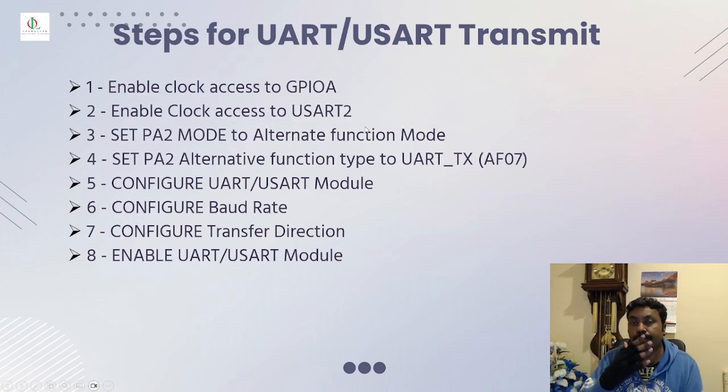If you cast your mind back to that LED blinking project, you would understand you have to enable that clock first, so that the microcontroller knows which port the input or output is coming from. That is why the user needs clock access, to alert the microcontroller. So that's a must. And every port and every peripheral is associated with internal registers, and that's how you write a program. You have to write a program to set, enable or configure those registers.